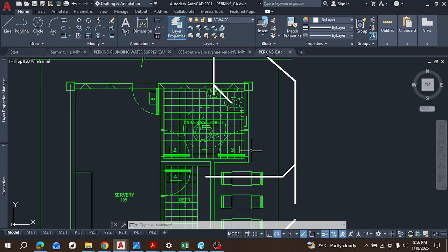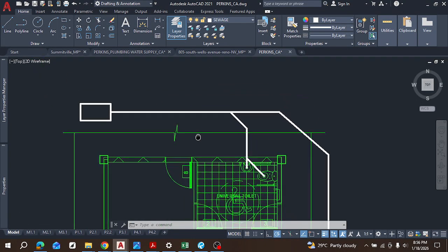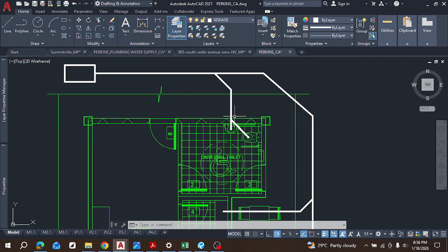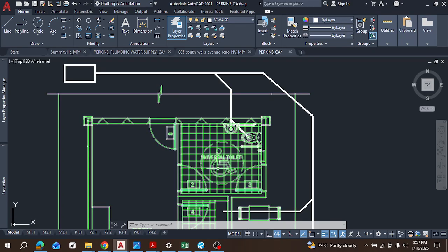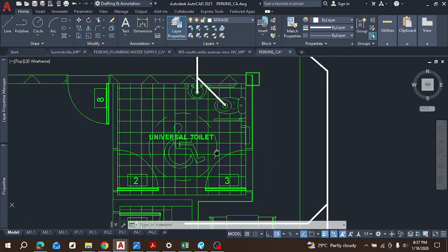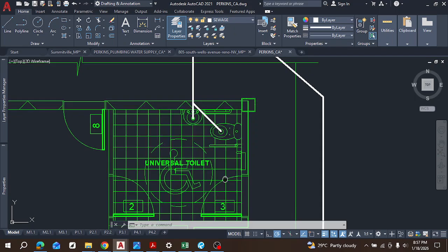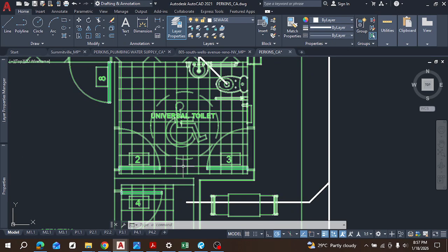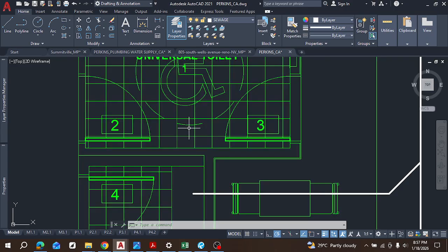A 2 inch pipe is going to be the largest pipe available in that system, so all of this is going to be 2 inches. Now this one that is serving only this place can be smaller, maybe 1 inch. Or it can still be 2 inch to be on the safe side, because there might be cases where you need to add a system to this. Now this should also have a floor drain. Even close to this one, you can put a floor drain here and make it pass through this guy, so it still serves out as one too.